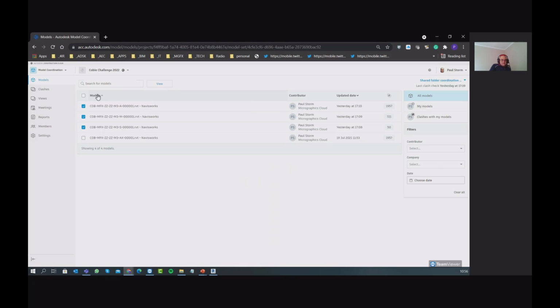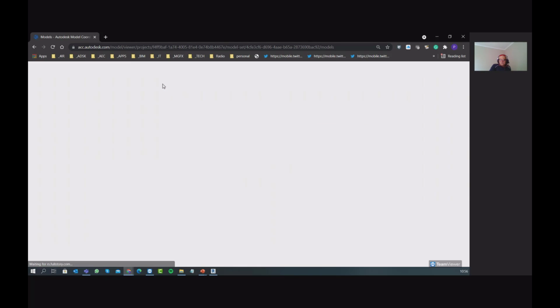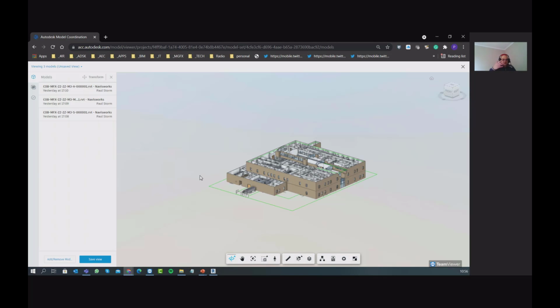And then I can say the view, and that will then generate a clash detection for me between those models, and that makes it very quick, very powerful, as opposed to setting everything up in Navisworks, creating selection sets and choosing what you clash against each other. It can generate a lot of clashes, so it helps to condition the models before the time. But that is why we would typically publish our files, say, as often as we need to inside of our own teams, but then once a week internally.